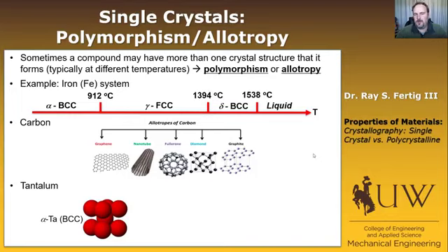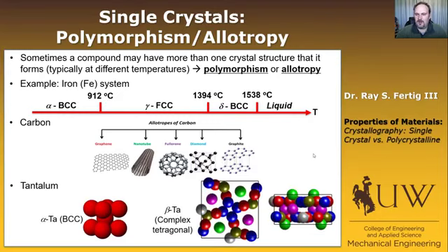But when we were depositing it in thin film form, that means we would buy a target of tantalum, hit it with plasma, and sputter atoms onto a very, very clean surface and create very high quality films of tantalum. And when we would create them in that fashion, we would sometimes be able to create a different crystal structure, much more complex. In this case, we called it beta tantalum. And it's a complex tetragonal phase.